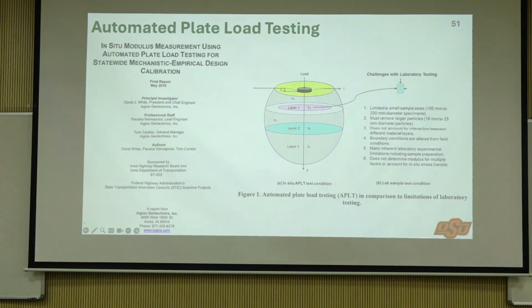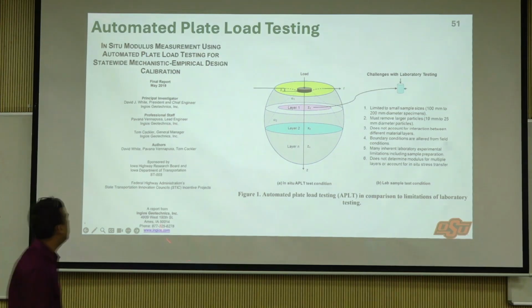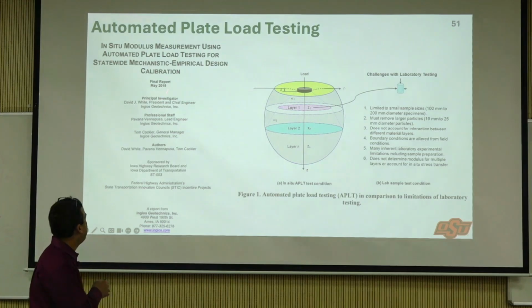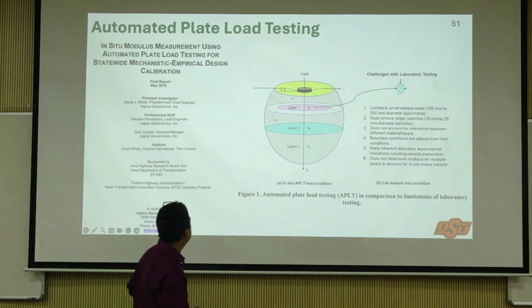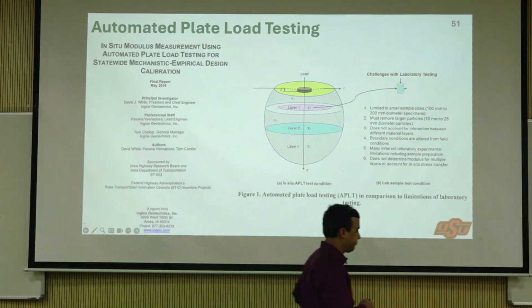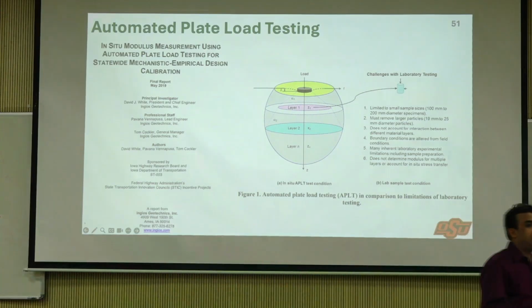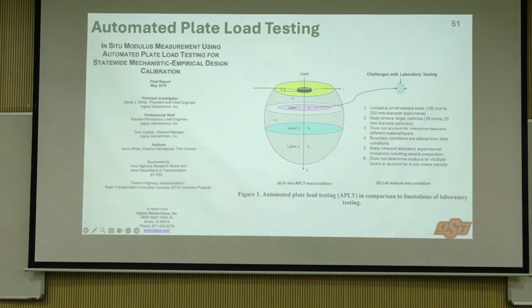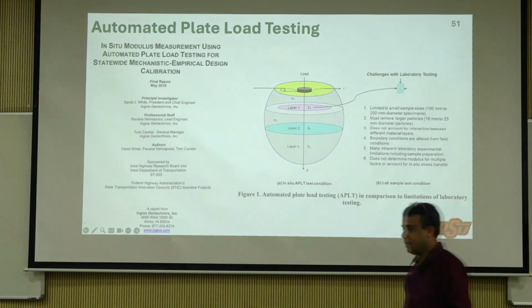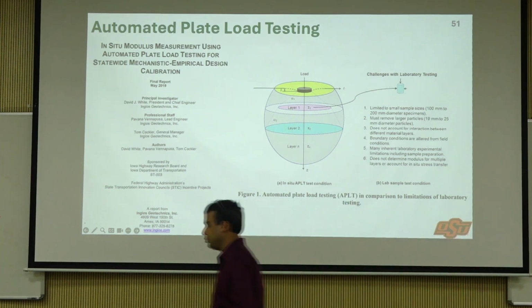This is David White, who was a professor at Iowa State before he became a private consultant, and Pavana Venapusa, who is actually from India. He was his PhD student and then postdoc, and then he became their lead technical person. So that's the plate load test for you, just an overview. You get modulus of subgrade reaction and try to link it with resilient modulus. There are disadvantages, but it is still used in practice.